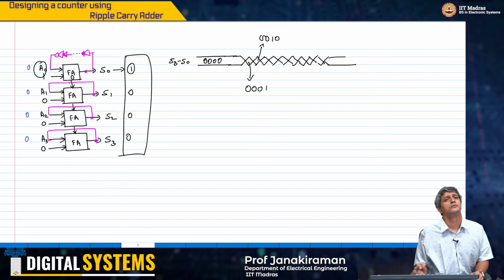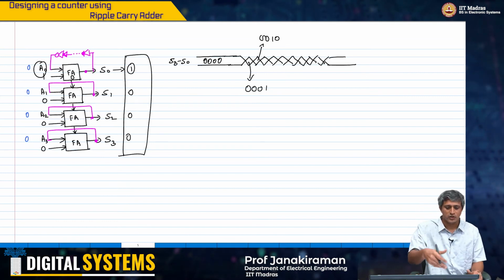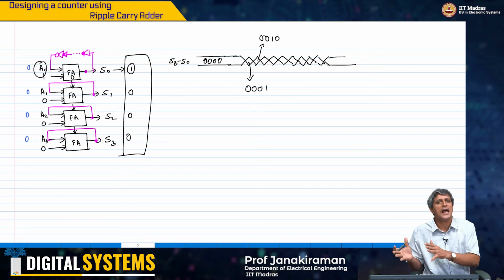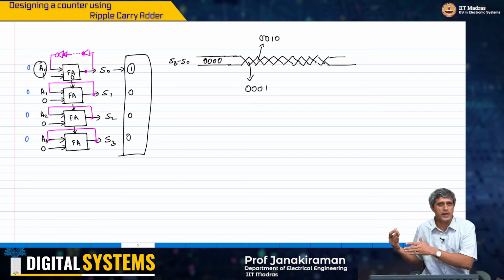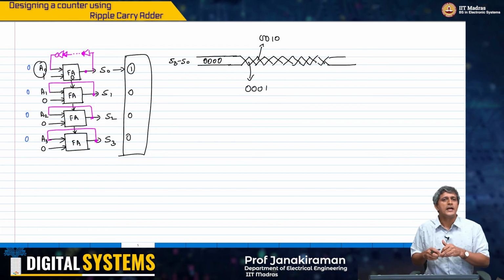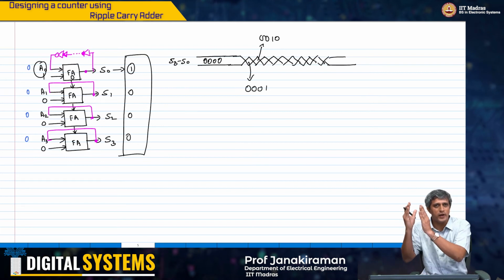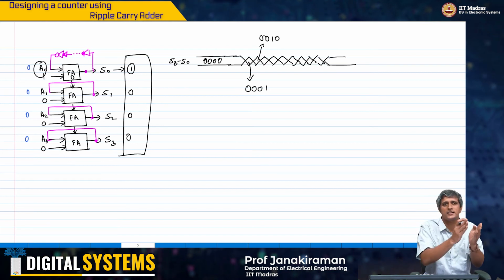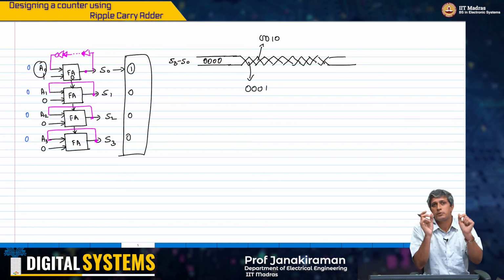for everything, right? But again, what happens is each of S0, S1, S2, S3 is going to react. They are all going to give you outputs at different times, right? Because of how the ripple adder is working. And therefore, it is not possible to get the state of S0, S1, S2, S3 back to A0, A1, A2, A3 consistently at the same time.